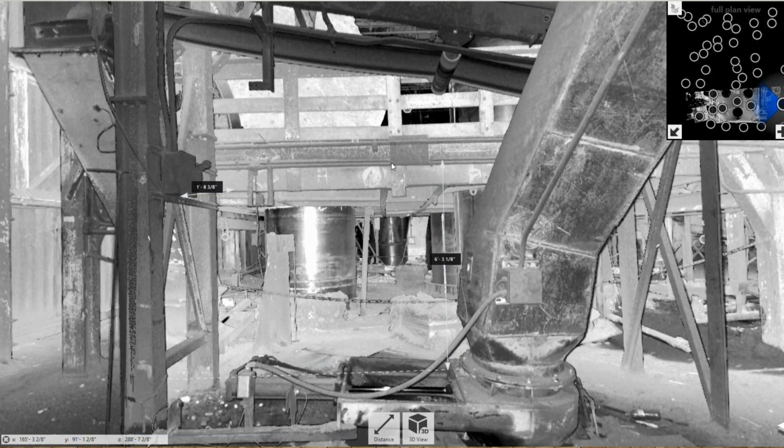When you're using AutoCAD and the scan is in AutoCAD, that granular picture is what you get. But when you're in Autodesk Recap, then this is the image you can get in the 3D view. You can get both views. You can get the laser scan granular, and you can get this photorealistic view that you can rotate 360 degrees. I've taken a few dimensions here, and you're going to see me take a dimension in just a moment.